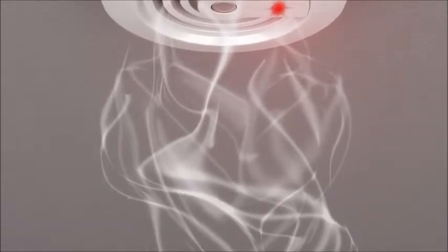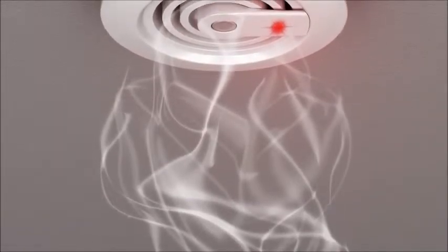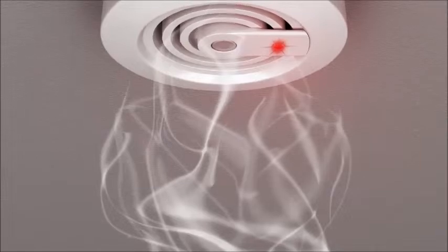Photoelectric detectors use a beam of light sent from a light-emitting diode, LED, that is detected by a photocell. There is a common misconception that the photocell receives light at all times from the LED, and when smoke gets in the way, the alarm is triggered, similar to the way a door alarm at a convenience store often works. This misconception ignores one glaring problem. It would require a large amount of smoke to block the light from the photocell, making it extremely insensitive. A person would be dead from smoke inhalation long before the detector would ever go off.